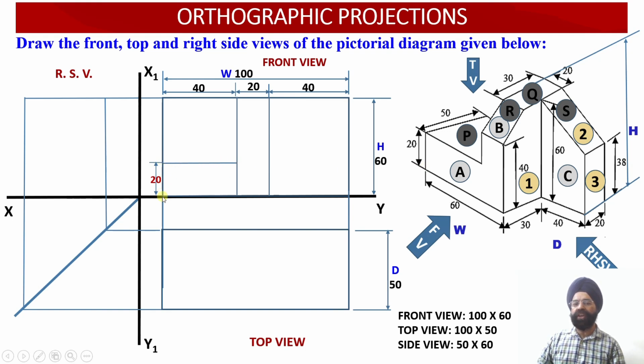So this portion of the web which is appearing on the left hand side has been constructed. First of all, height I have marked as 20 millimeter. The width has been marked as 40 millimeter over here. So this height has been transferred onto the right side view because this will be available as a dotted line as we are going to look at this particular web from the right hand side. So the projection line has been drawn even in the right hand side view.